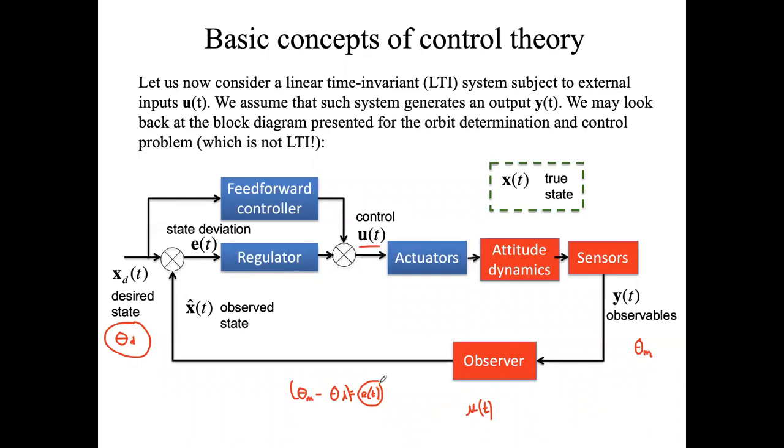So as I said, we are introducing them now because the reaction wheels have the possibility to change continuously the velocity of the wheel, and so change continuously the speed, the torque that you are going to apply to the system. You are not able to use thrusters in this scheme because, as I said, the thrusters work with the maximum torque for a specific time, tau. That's the reason why the bang-bang approach is the one that you have to use for thrusters.